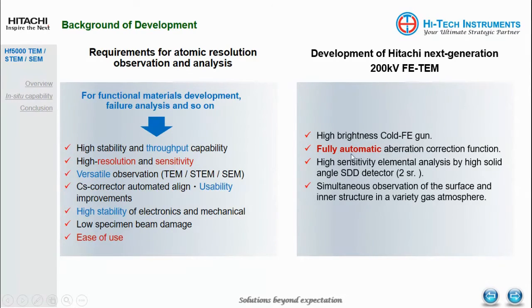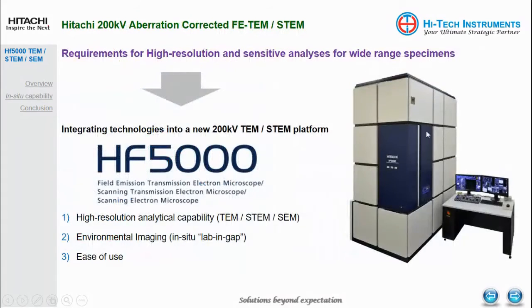And it comes with a fully automatic aberration correction function developed by Hitachi, and high sensitivity elemental analysis by high solid angle SDD detector, and simultaneous observation of the surface by the SE detector, and the inner structure in a variety gas atmosphere, this one by STEM detector. And this one you can actually induce a gas.